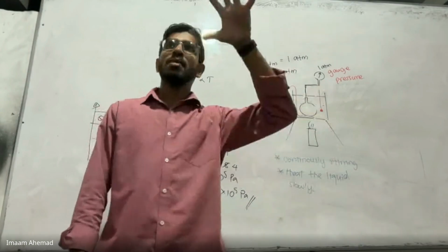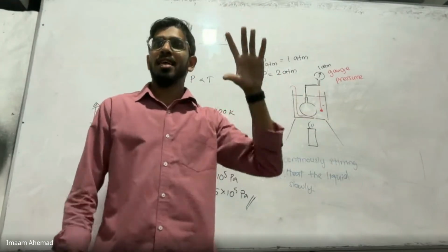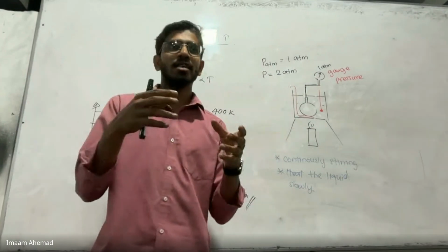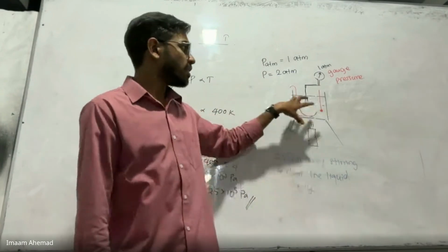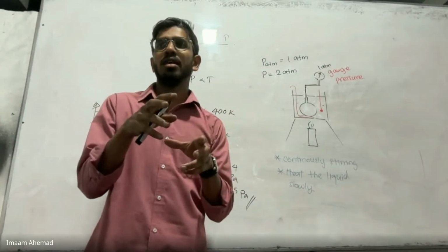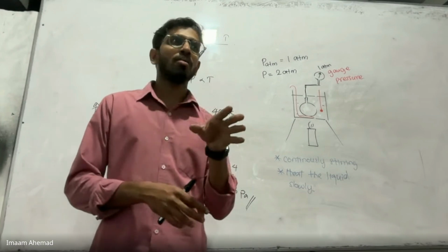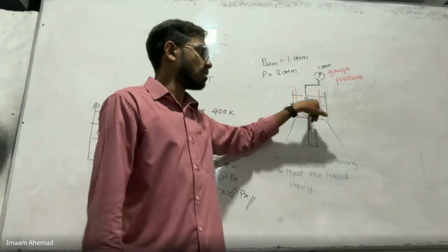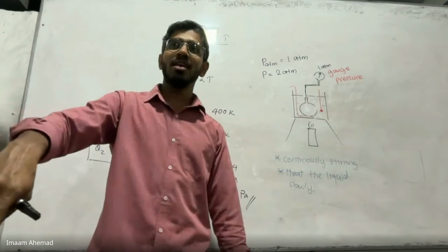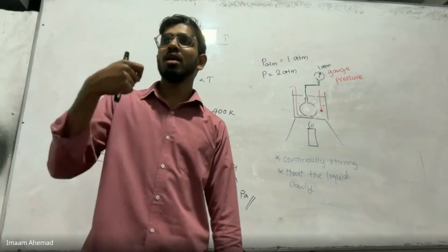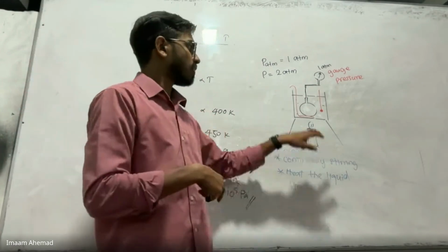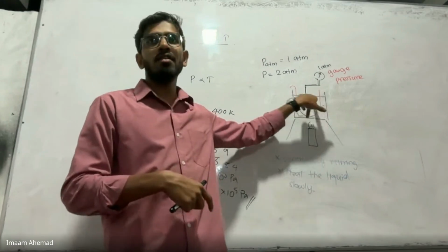If you're using a larger bulb, then what's the problem? Air is already a poor conductor, so it will not spread the heat equally. But if it is a smaller one, then it can easily spread the heat uniformly and come to a common temperature. So one solution would be using a smaller bulb. What I told earlier would satisfy if the question was how to minimize the error. But if you want to have equal temperature, we will have to use a smaller bulb.